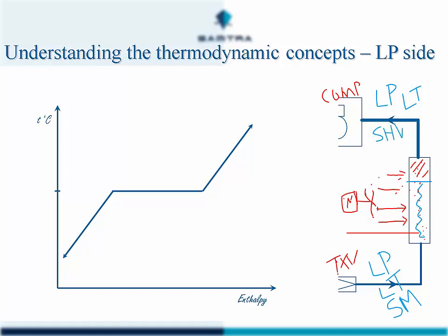Okay. So the air that passes into the evaporator through the fins around the outside of the copper tubes or pipes loses its heat energy to the refrigerant, and it will come out colder, and that will then pass into the room, hopefully collecting more heat energy, reducing the temperature or removing heat energy from the cold space.